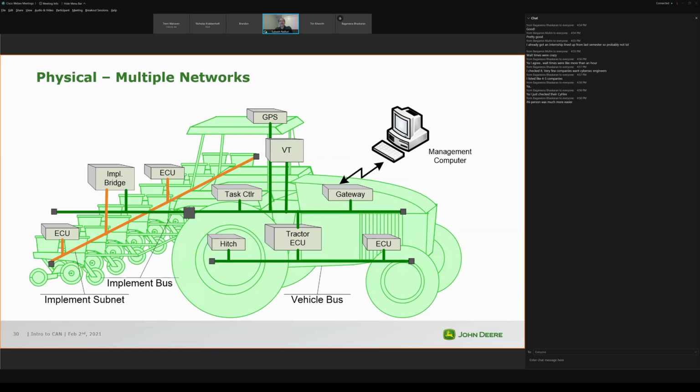with CAN-FD, you have to design the controllers to support it, which means that the low-level hardware should support the CAN-FD. Either it's tolerant so that it doesn't throw errors, or it is compliant so that it can read it, understand it and respond to it.